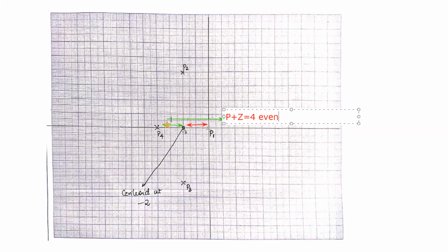This region of the real axis cannot be a part of root locus. Your root locus will not go here at all. From minus 2 to minus 4, you will not have any root locus. The system will not have any line or any locus. It will not go from this region to this region. There is no question of it having a root locus in this region.